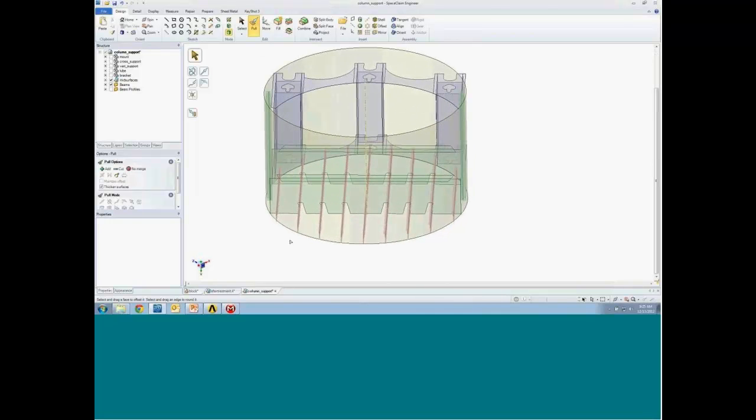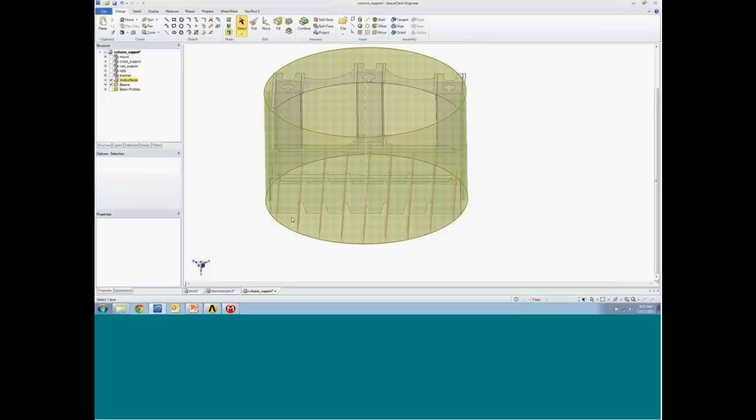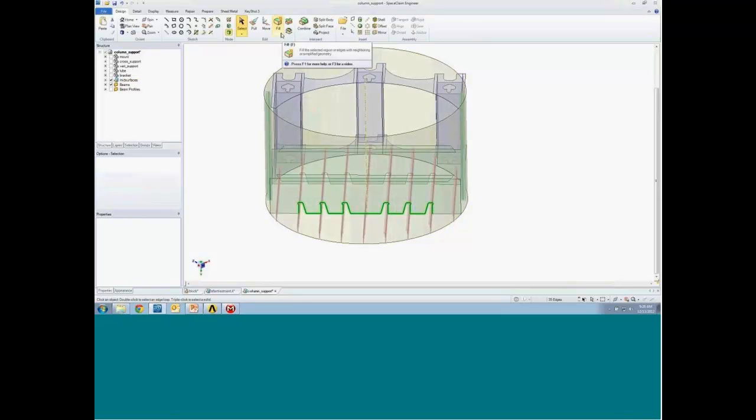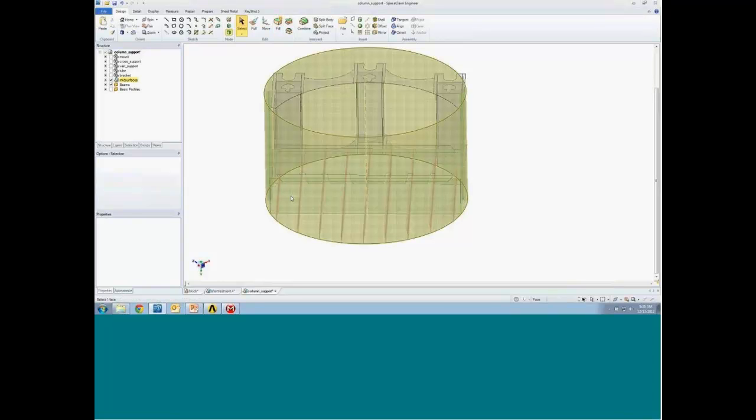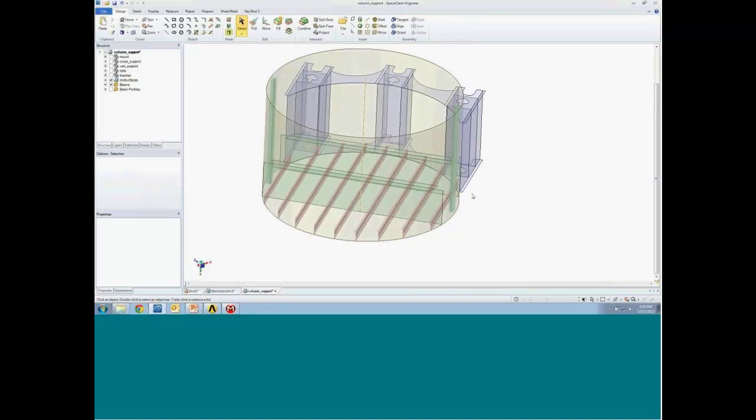Now, before I go in and start taking care of edges and node points, I may say, let's take that mid-surface, there's a couple of them in the middle, and get rid of all those edges where the cross-sectional members go through. It's as simple as taking edges and filling them in. I mean, that is just lightning fast what SCDM does. It's simplifying all those edges and just extending out the natural progression of that face.